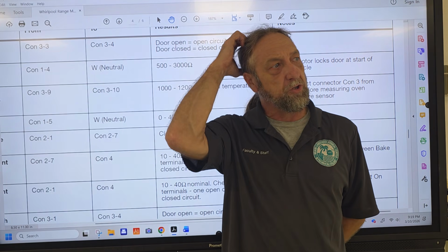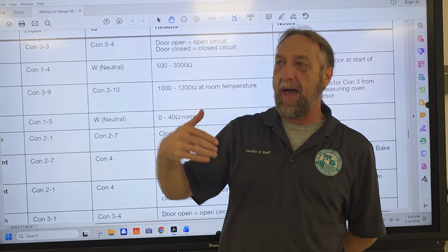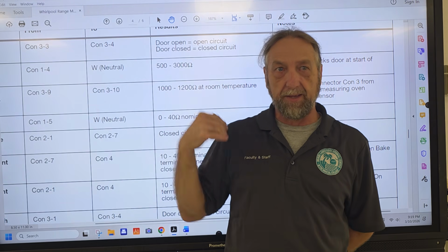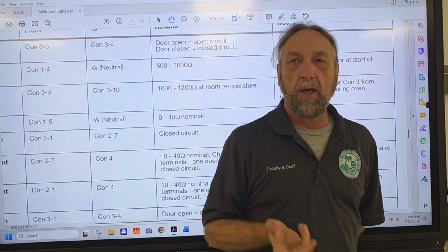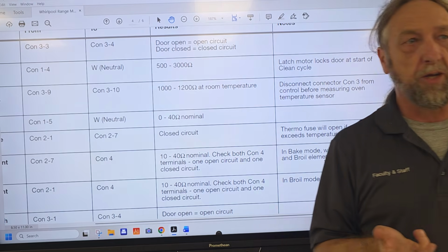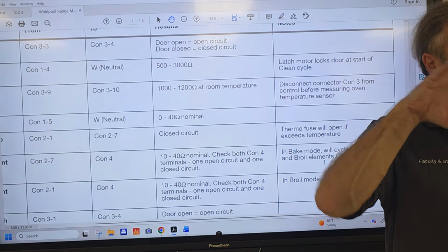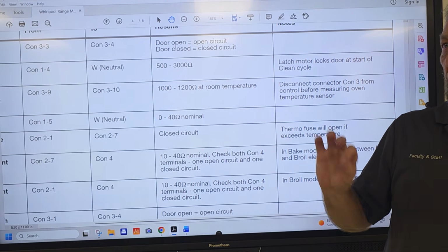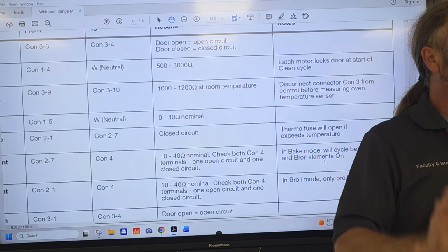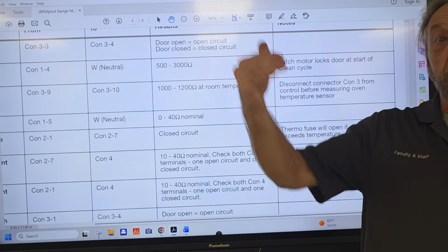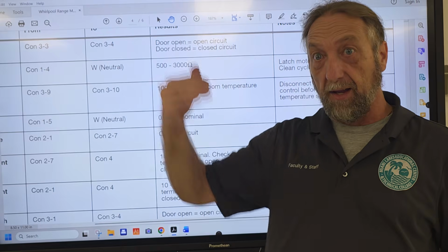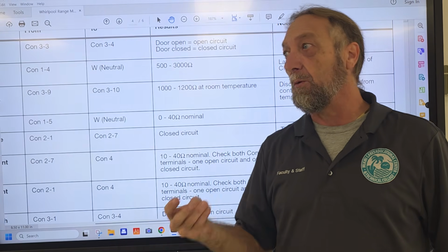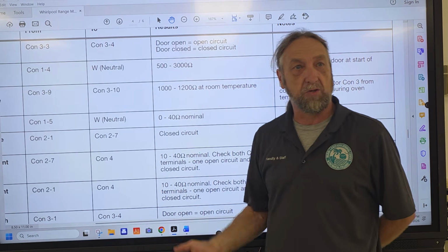And they're like, well, why did you do that? The resistance value is usually about half what it would be on these here. And they said, well, testing from our engineers determined that the lower resistance value thermistors were more accurate in controlling the oven temperature, the cut-ins and the cut-outs. We found out that they were more accurate, so we went to this new sensor.